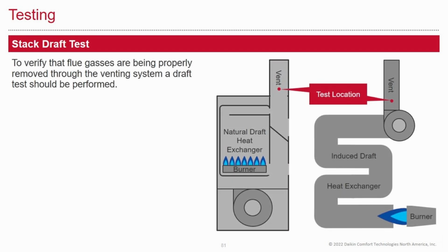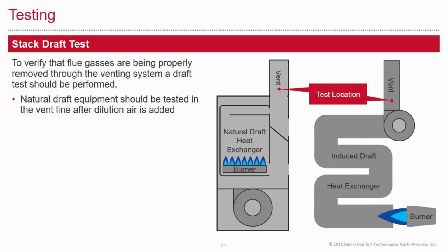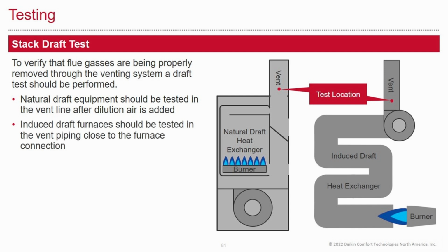Stack draft test. To verify that flue gases are being properly removed through the vent system, a draft test should be performed. Natural draft equipment should be tested in the vent line after the dilution air is added. Induced draft furnaces should be tested in the vent piping close to the furnace connection. Condensing gas furnaces do not require a draft test.